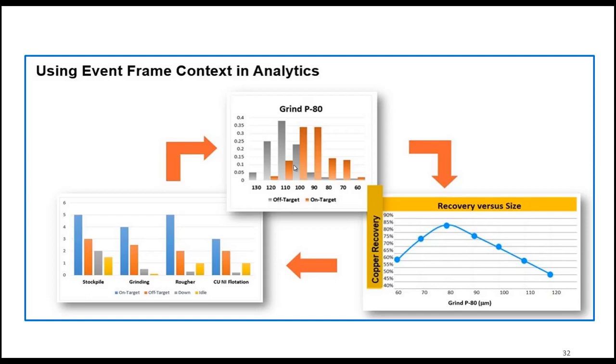And most importantly, the shape of that curve distribution is important. So if you do have an analyzer, you can develop a shape analyzer, and then you can relate your shape with the recovery so you optimize the speed at which you're running the mill to get the right size so you don't have indigestion in your system. That's a metaphor that I use a lot to explain to people how this works.